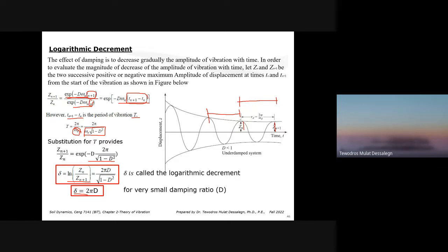If you don't know, for example, the damping of the soil, you can do a free vibration test and get two amplitudes, anywhere you can measure, then you can find the D. That's where it's practical. We will see how to calculate the damping values of different materials at some point, but this is one main concept we use to determine damping ratios.